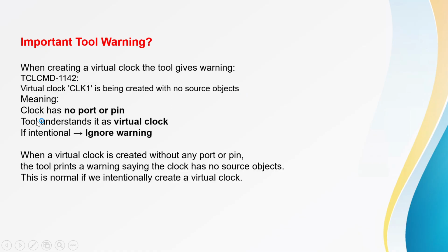It means the clock has no port or pin, so it will be understood as a virtual clock. If it is intentional, you can ignore the warning. So when a virtual clock is created without any port or pin, it will give the warning.